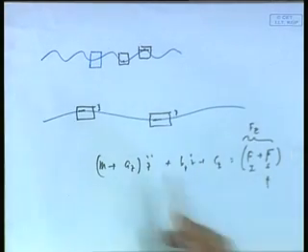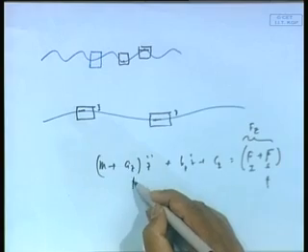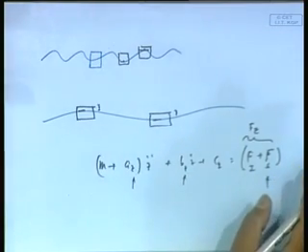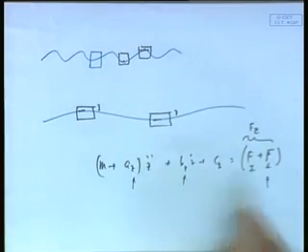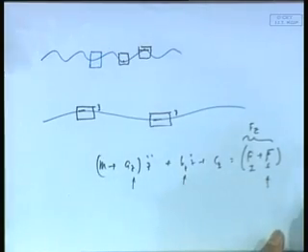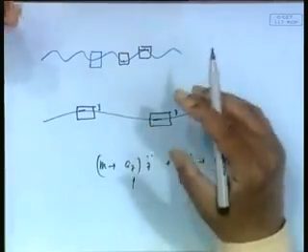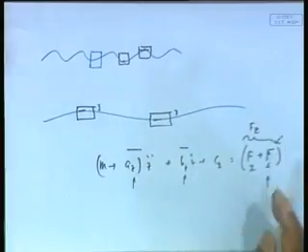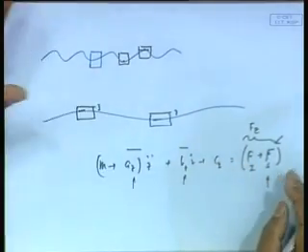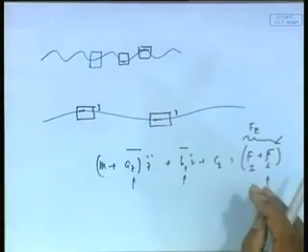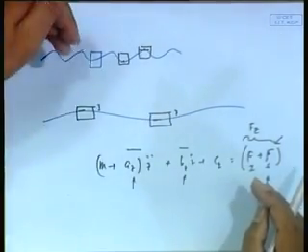And let us say you are doing a solution and you made a mistake in this estimate, which is of course very usual to do, because hydrodynamics is in this and this and this. So in a static dominated force, there is practically no hydrodynamics. You can make all the mistakes in hydrodynamics and you still end up getting a good estimate. In an inertia dominated force, which happens to be more critical in some sense because it is out of phase, you unfortunately are required to have a good estimate of this force and this force and this force, because it is the hydrodynamic forces that decide inertia dominated motion, and it is in inertia dominated motion that I typically have a tendency for the freeboard to change.